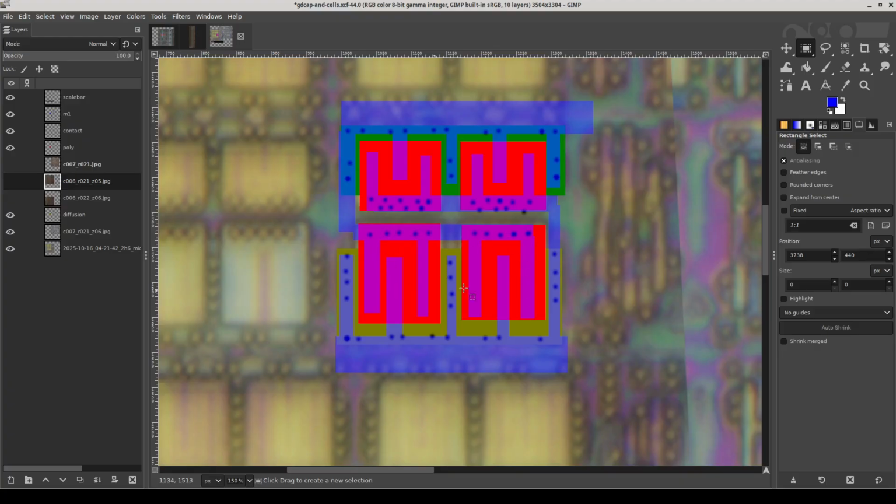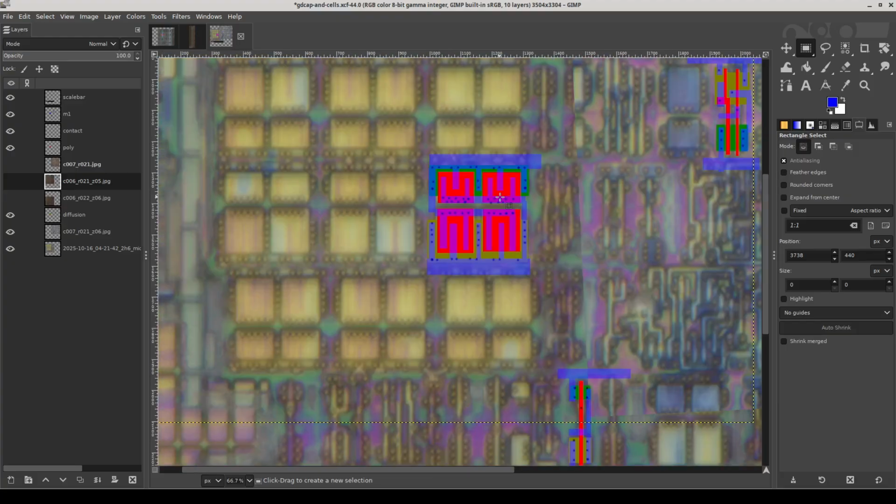So essentially this whole big thing is a capacitor from VDD to ground, and we have a capacitor from ground to VDD here. So this entire thing is essentially a decoupling capacitor for the internal core power rail that is being used to stabilize the power and also presumably as a dummy filler whenever there's a region of cells.